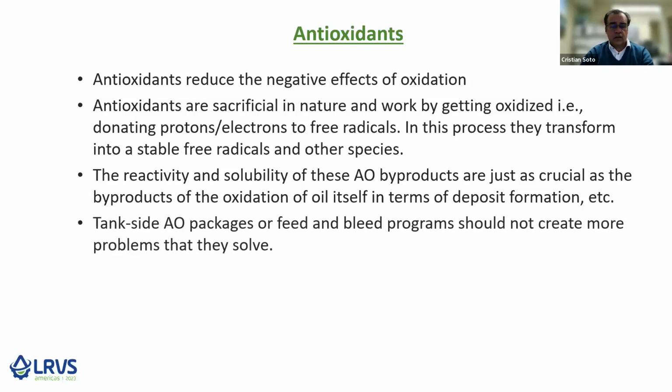Therefore, tank-side antioxidant packages or feed and bleed programs, which are meant to extend the life of the oil, need to be selected carefully in order not to have deleterious effects due to incompatibility primarily, as these incompatibilities may work against the overall performance of the lubricant.